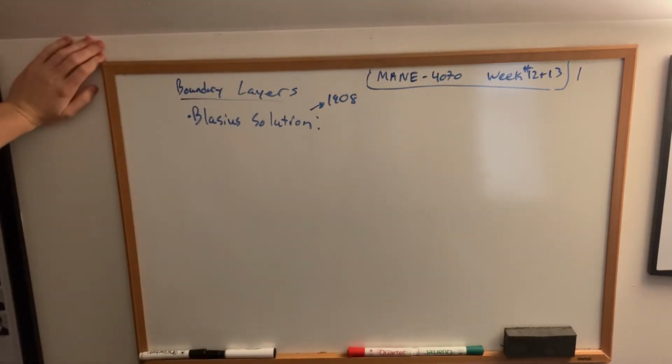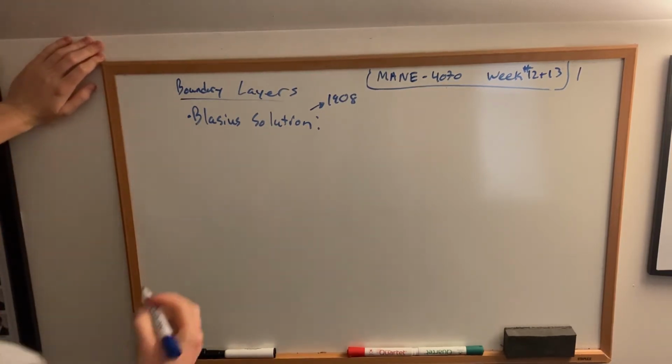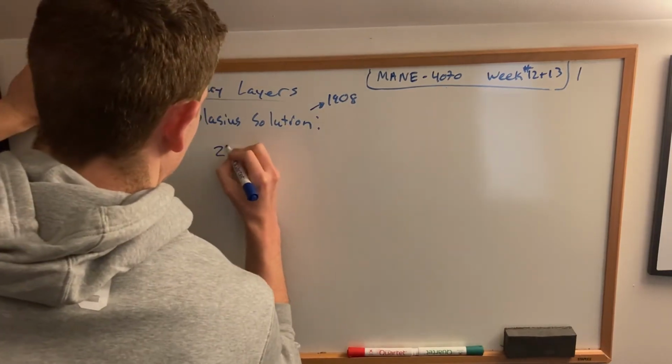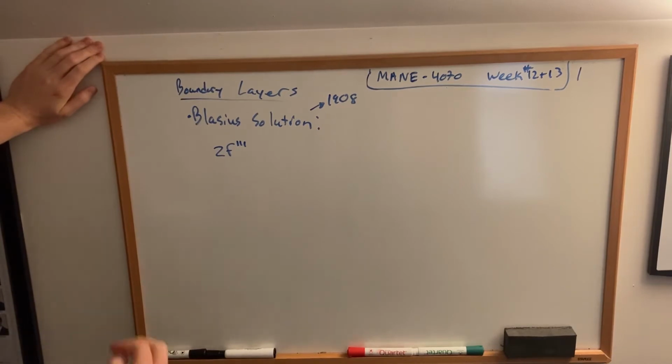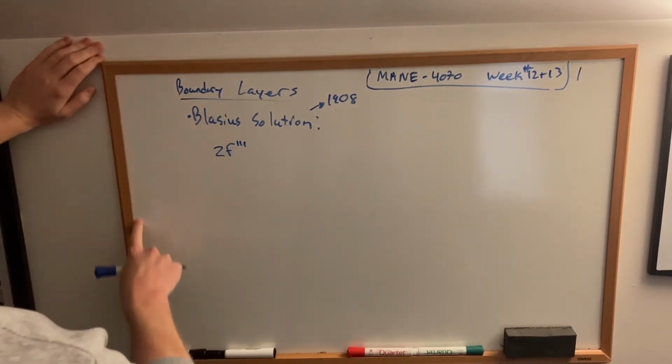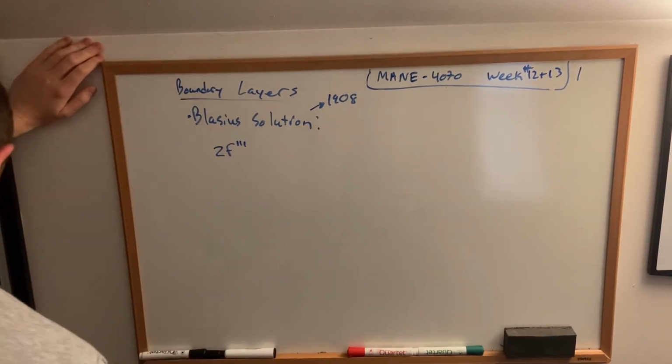And it's essentially an ODE that uses the self-similar results of a boundary layer to define it in a readily computable way. And I don't think we actually went over the actual equation in class, because at this point in time, we don't use it generally. People like to just take Blasius's results as opposed to his solution itself.